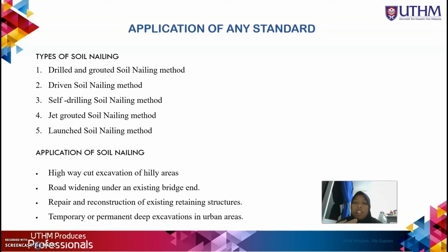Next, driven soil nailing method. It is used to temporarily stabilize soil slope. The driven soil nailing method is quite rapid. However, it does not protect the reinforcing steel or nails from corrosion. The nails in the driven soil nailing method are driven into the slope face during excavation.